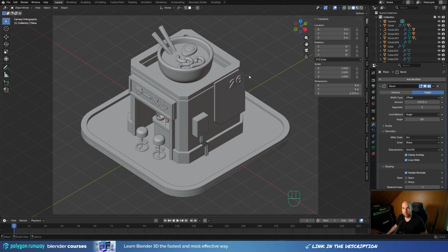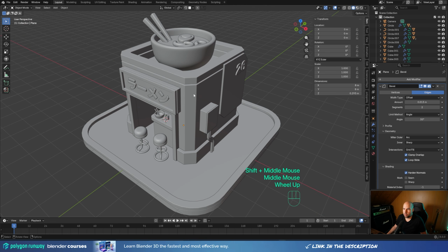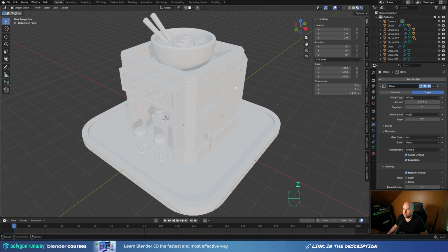Now let's bring in some materials, and what I like to do is to keep colors and materials pretty limited and reuse them as much as possible, and that way you will always get a more coherent result than if you just go wild with your colors and create a material for each object separately. So for example here, I really want to make this wall bright, have a lot of metallic objects in the scene, and then some accent color, for example red. So let's hold Z, switch to the material preview, and let's start applying some of these materials.